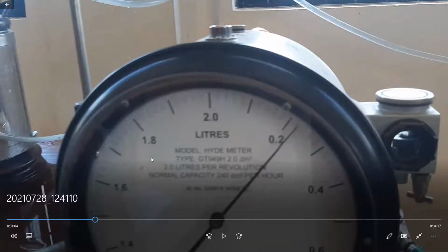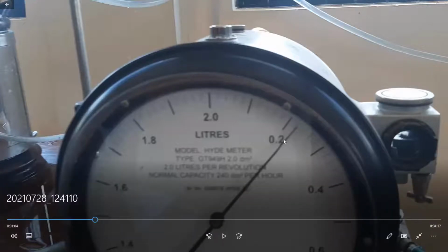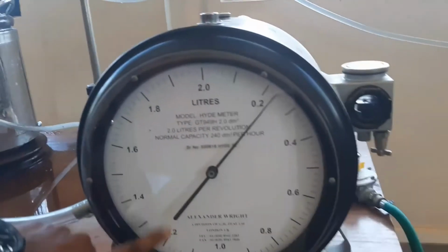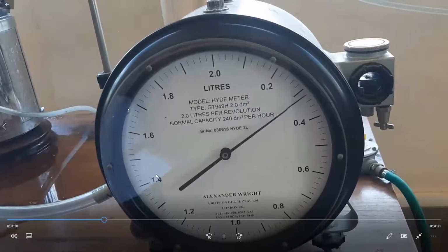we can calculate the volume of gas flow through this meter, or the volume of gas burned inside the furnace, while collecting 1 liter of water. That is equal to the volume of gas flow through this meter, right? So while collecting, we have to look into this meter when the volume of collected water becomes 1 liter. Here we can also measure how much gas is burned at the same time, right?